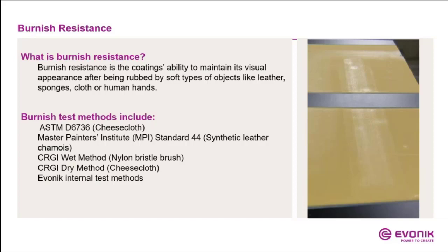In all of these test methods, it is more or less the same procedure. You treat the surface with a soft device, and then you measure the gloss difference before and after treatment of the surface.